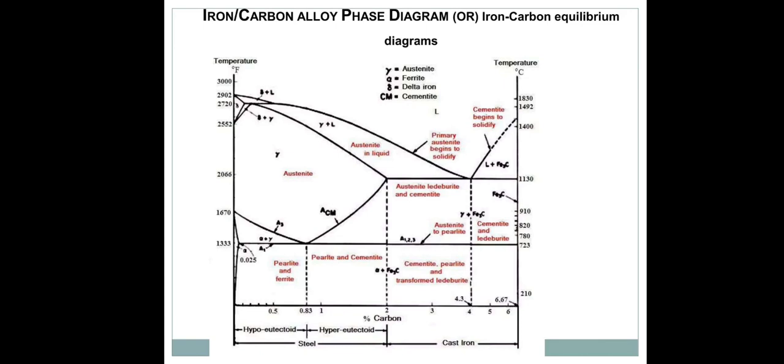Here we can see the pearlitic structure of alpha plus Fe3C, the eutectoid of ferrite and cementite, with a laminar microstructure of alternate alpha iron and cementite plates. Like this, microstructures such as pearlite, ledeburite, martensite, troostite, and sorbite are structures we can get in this iron-carbon phase diagram.